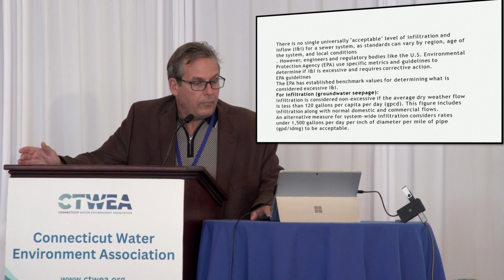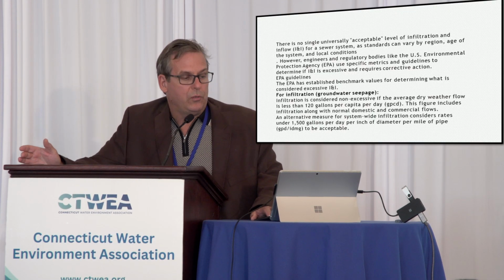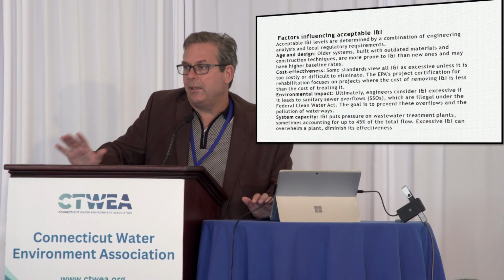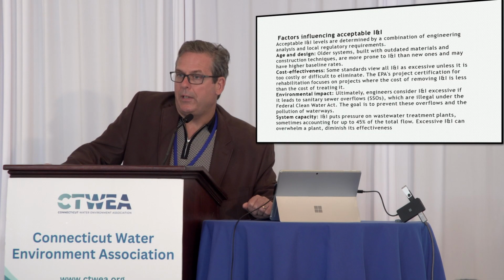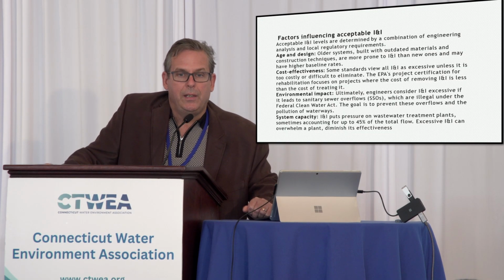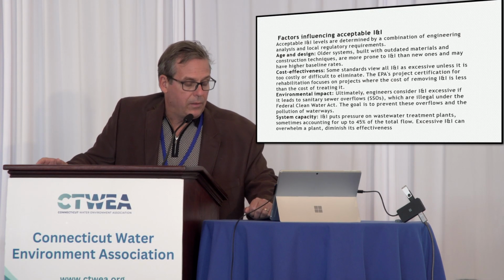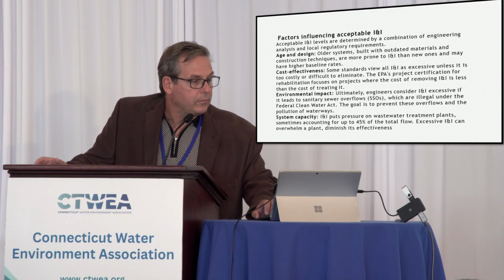But again, initially that surge of water that comes into the plant from a high water event can push all your solids out of your aeration basins into your secondaries, and that's where you can potentially have non-compliance events if the sludge blanket gets too high.